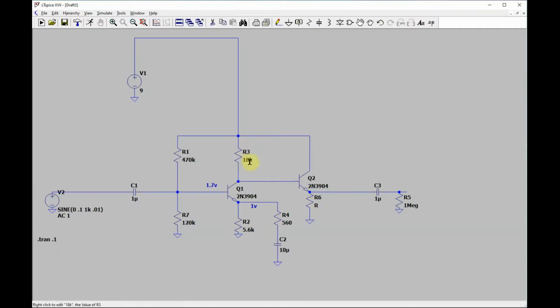This is the output impedance of the amplifier, going into this next stage. So if this is 18K, you need at least 180K here if you don't want a lot of signal loss. So how do you get this to be 180K input impedance into here, that is, the base?